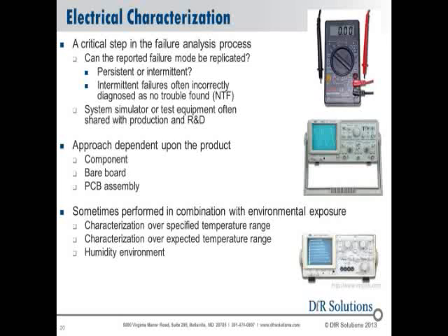So things like vibration and shock, the temperature, thermal cycling, humidity can all affect the part in the field, causing a malfunction or failure that rights itself and the part was working when it comes back. So if you're getting a bunch of these no-fault founds, you want to develop a methodology of exposing it to various types of environmental stresses like temperature, vibration, or humidity to see if it continues to work under those conditions when you are looking at it in your FA lab for its initial confirmation.